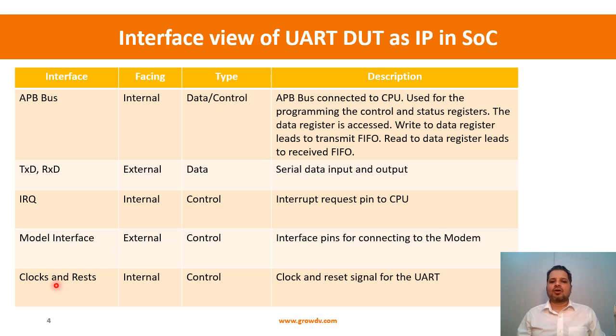And then you have clocks and resets, which, if it is a part of a SoC, are internally fed. Your SoC will have internal PLLs to generate different types of clocks, and these clocks and resets will be fed from there. So it will have a centralized clock and reset handling logic inside the SoC, which caters to all the IPs, and that will feed our UART as well.